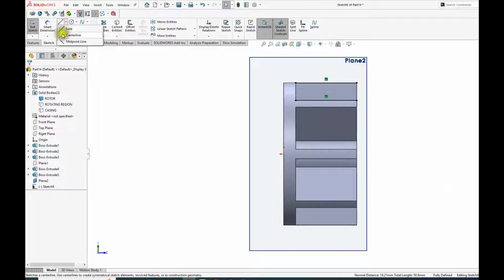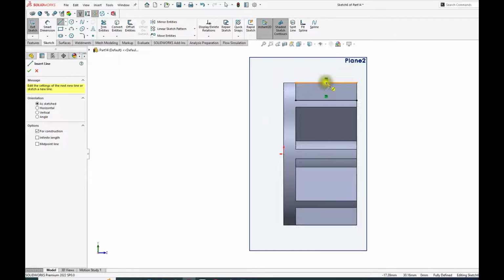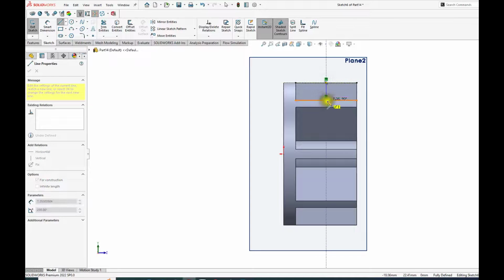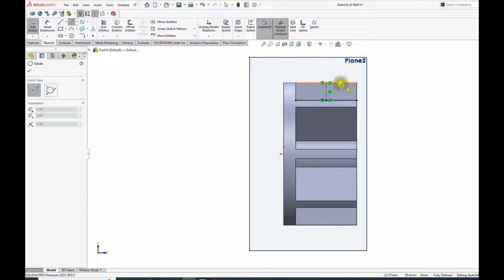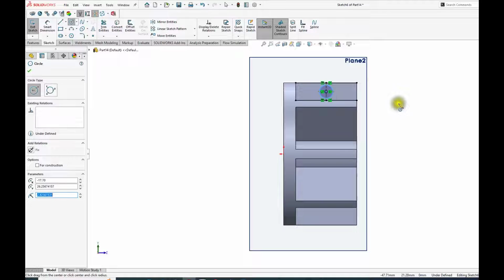Now let's do a center line here, right at the center here, and the center here. That's a construction line. And from the center of these, we want to do the inner circle for the water flow. So let's do this and right there. Now don't hit the borders, because it would try to tie them to some specific side as related to either of these 2 points.